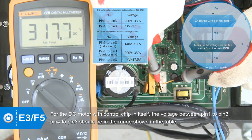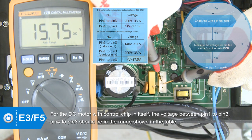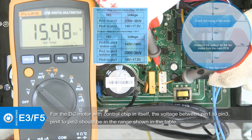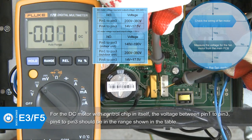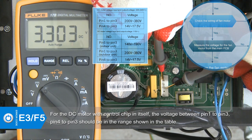Examination for main PCB board: DC motor with control chip in itself. Turn the power on. When the unit is in standby mode, measure the voltage between pin 1 to pin 3, and pin 4 to pin 3 in the fan motor connector. If the value of the voltage is not within the range shown in the table,